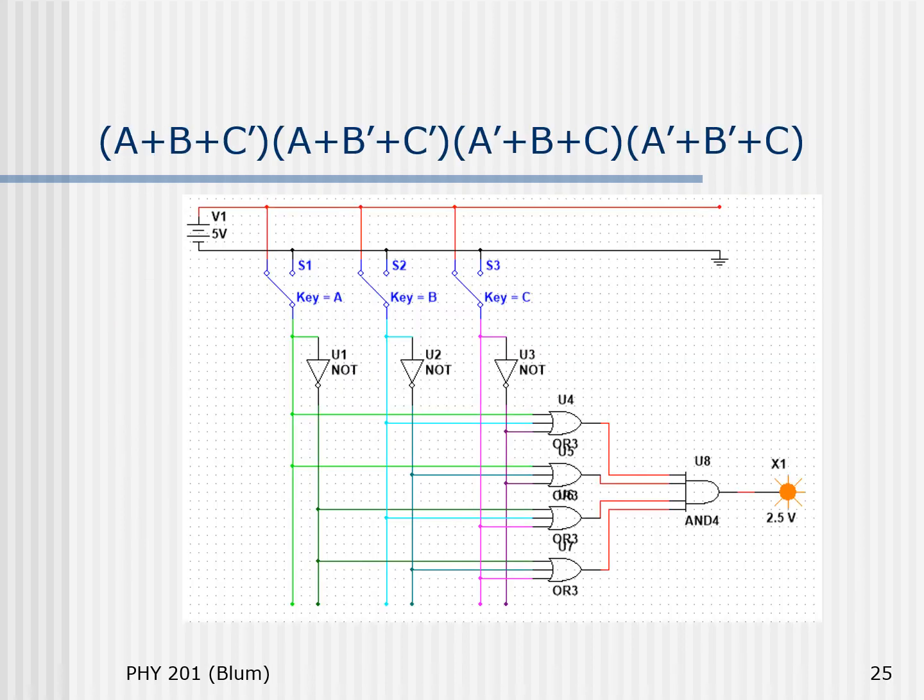If we are going to build this using gates, the top portion is the same, that there's a battery and that there are switches connected to the battery. So there's an establishment of a low state and a high state, and then connected to the three switches, the A, B, C switches, are not only a line that comes straight out of the output, but also a line that goes over to a NOT gate and inverts that output, so we have access to both A and A prime. That part was the same. The difference is now that we have ORs before we have an AND. Previously the ANDs came first and then the OR, but now we have switched that order and the ORs come first and then the AND.